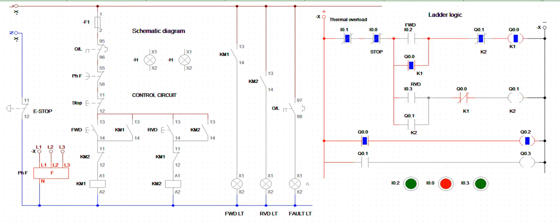When this one is running and I try to activate the second operation, look at it. It cannot go because the auxiliary here is open. This auxiliary interlock, electrical interlock here, is open. So it cannot go until you deactivate the first operation before this one can go. And once this one is running, this one cannot go as well because the interlock is there until you deactivate